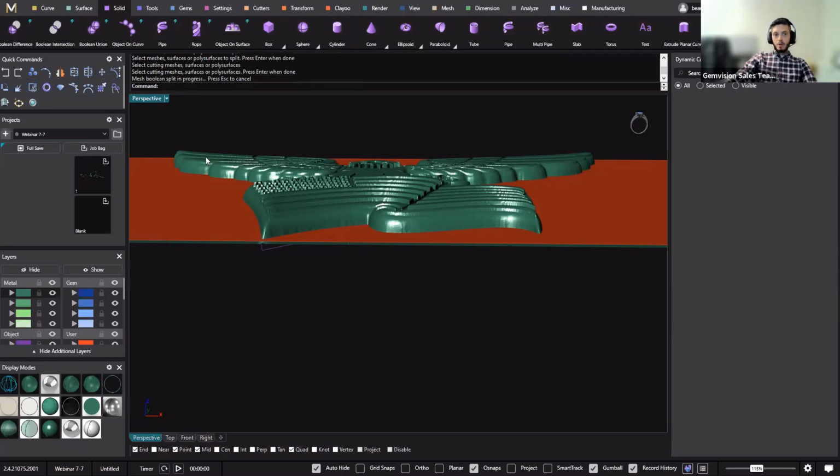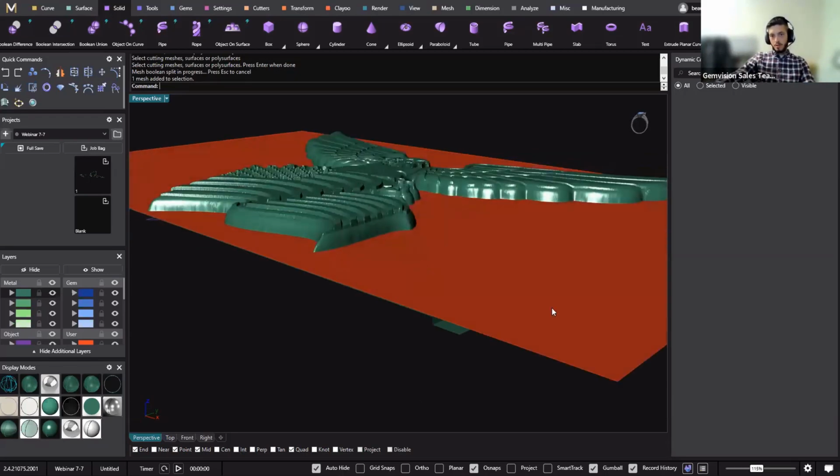If you go into the launcher, Roma, I would always recommend opening from the launcher, not just double clicking the MatrixGold icon, because when you go through the launcher, it'll check for Rhino updates, it'll check for MatrixGold updates, system updates. So going through the launcher, if the launcher doesn't say update MatrixGold, you're good. If it does, then you update through the launcher.